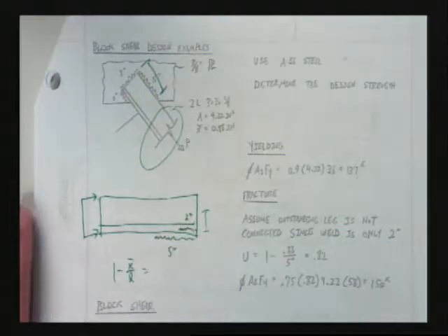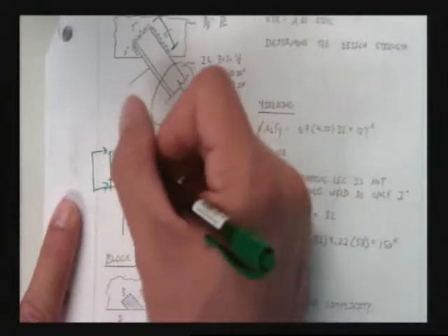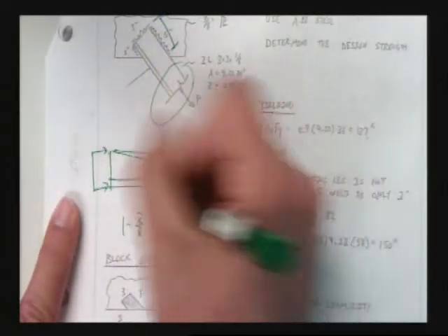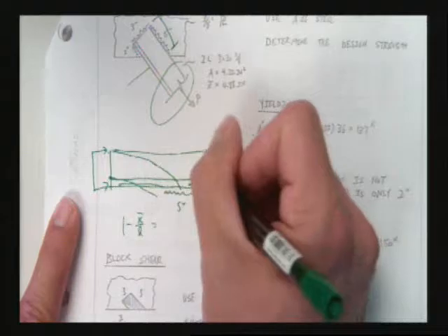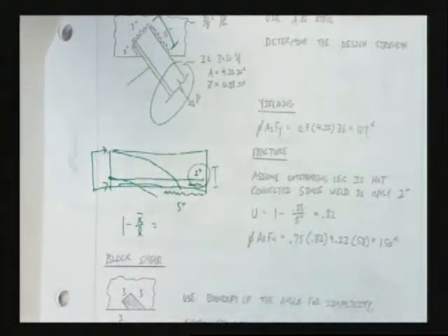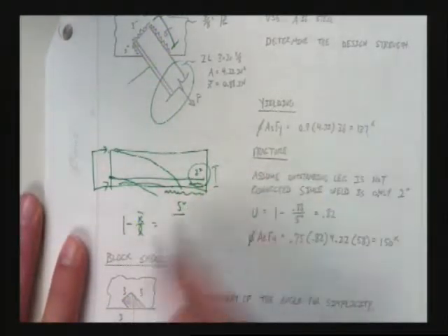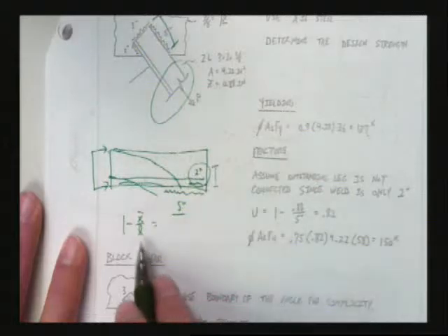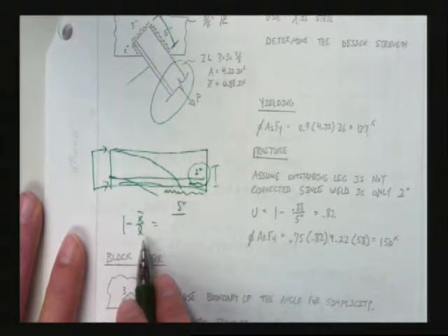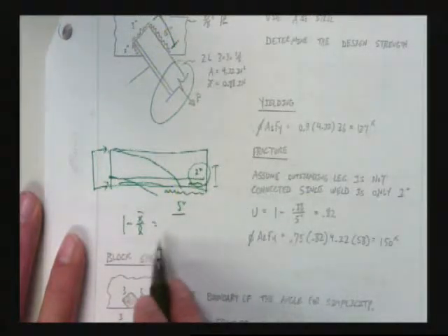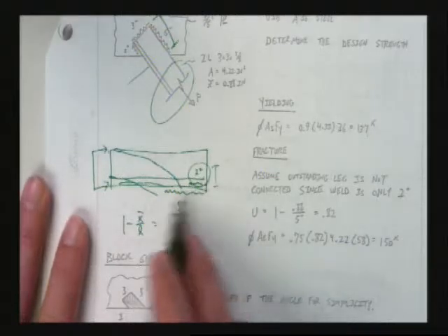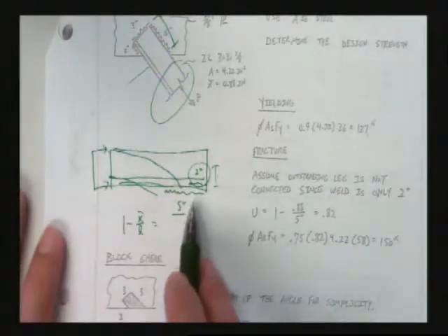So we're really going to want to get this stress out of here as much as we can before we get to this 2 inch. It's just not going to help us that much, right? Now, 5 inches is one way to handle it, and if we have a constant up here at the top, and I divide by 5, that's going to make that constant smaller, right? So 1 minus a smaller constant gives a less conservative number, right? But that's one way to attack the problem. Okay, now, could one maybe see where you might use the average of 2 inches and 5 inches?